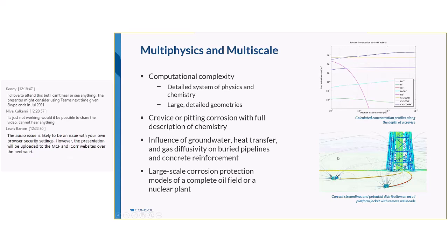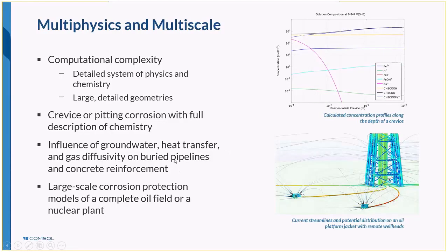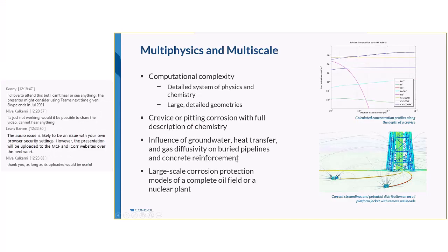And the main advantage of COMSOL is our multiphysics approach, so we can bring in extra factors such as heat transfer and transport of species to examine how, say, oxygen transport within our electrolyte domain influences our corrosion rate. And we do have a number of simplifications available for helping you model large-scale structures as well.